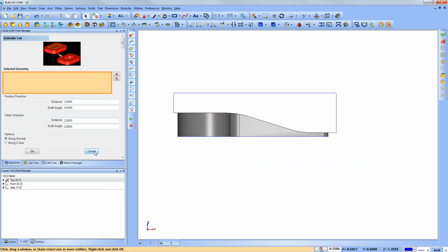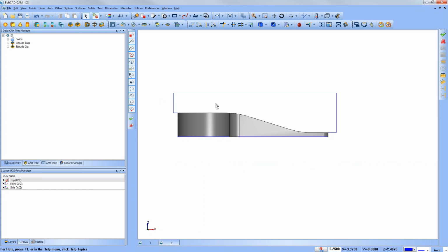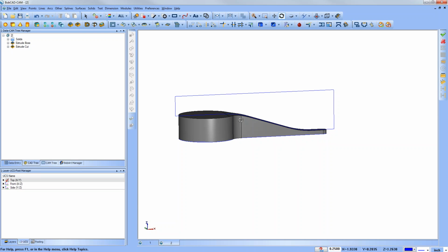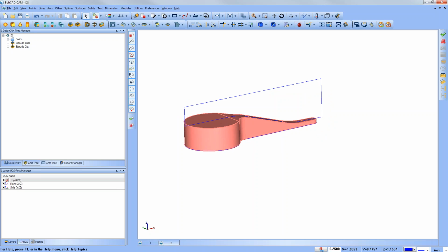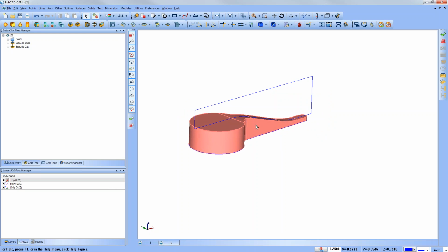If you wanted to make some sort of revision, let's say this is coming a little bit higher, you'd want to make sure that your wireframe chain compensates for that, or is within size. Otherwise, it doesn't really matter what profile. You could have a circle or half circle here. You could have really any shape. As long as it's larger than what you're trying to cut through, it'll give you the result that you want. Are there any questions on that?